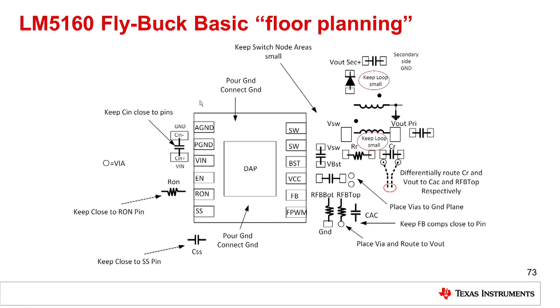Now, layout, of course, is a very important concern for any type of switching regulator, whether it's a buck or boost or Flybuck or anything else. This slide shows some of the most important considerations for any kind of a switching regulator. First, make sure that your input capacitor is very close to the power and input pins of the IC. Some of the auxiliary components, such as soft start and the R-on resistor, in this case for the LM5160, should also be placed physically very close to the IC.